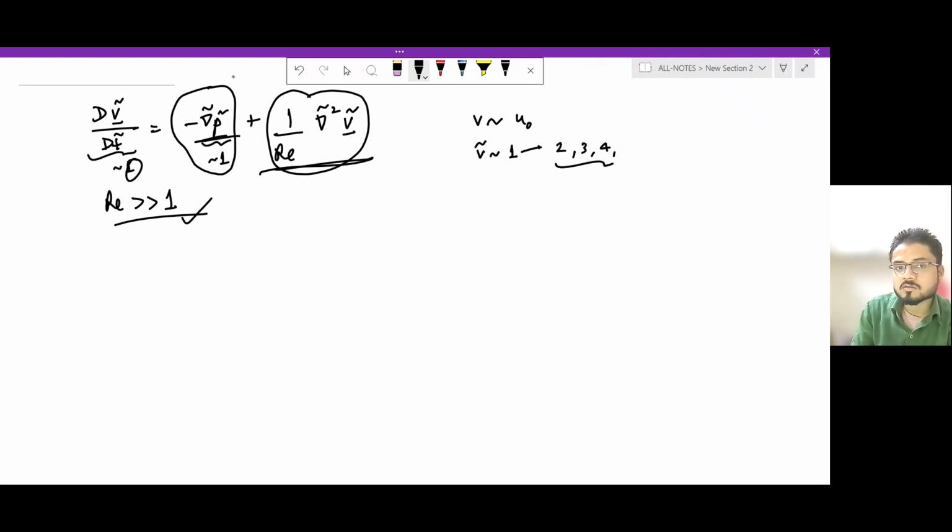All right. So this means that the viscous effects could be temporarily neglected. This reduces the Navier-Stokes equations to something like minus grad P. So we see that the flow is entirely pressure driven, and the viscous terms are pretty much neglected. So this is what happens during turbulence.